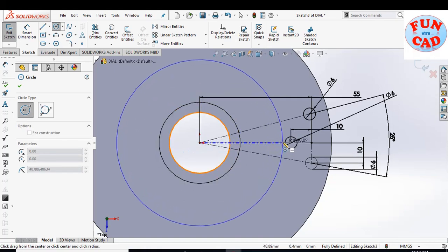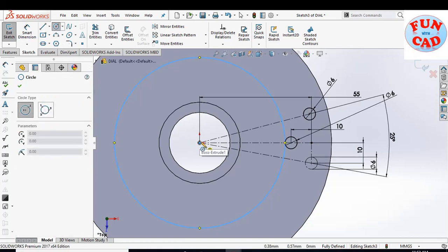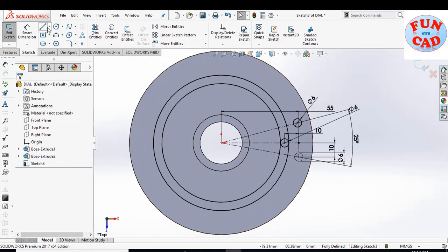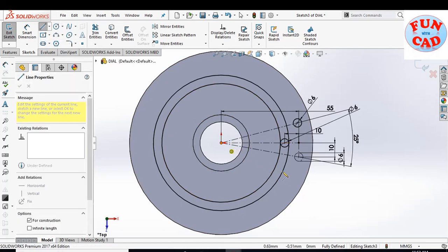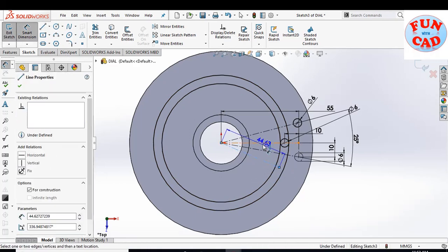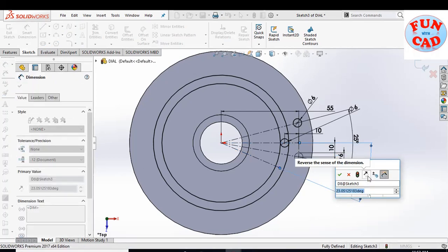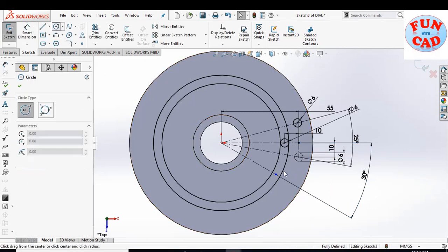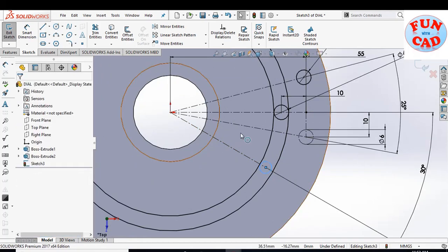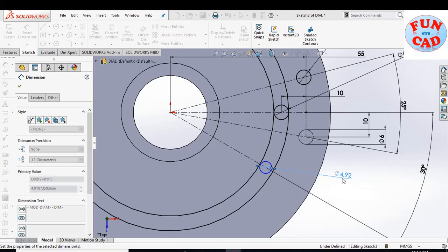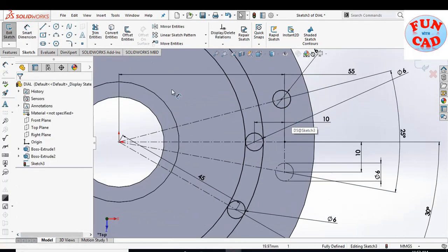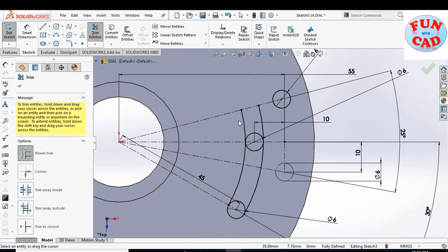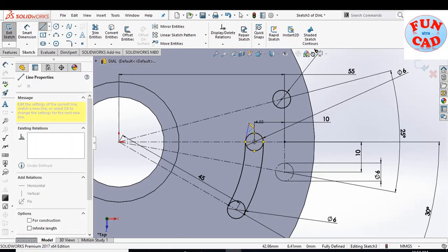As we don't want other side switch to operate, we will make some free slot on dial which is in circular trajectory. We will define 30 degrees of free rotation. Trim the extra parts. Now join the remaining part of the slots to be created.